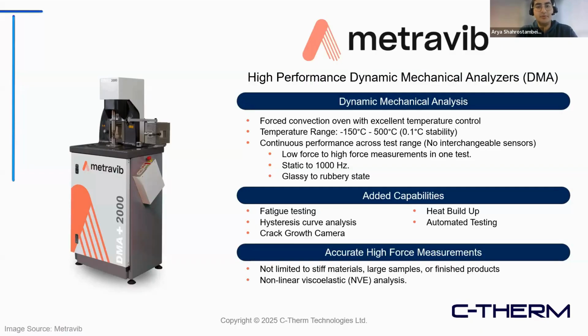And they are suitable for testing materials from a range of very soft materials to very stiff materials, and in a variety of frequency starting from 10 microhertz, so very low frequency, to higher frequencies as 1,000 hertz experimentally without any correction. And everything is measured during the experiment. The temperature range for this series starts from minus 150 with liquid nitrogen to 500 degrees C. And as Richard mentioned, you can have access to minus 70 using a chiller without having liquid nitrogen.